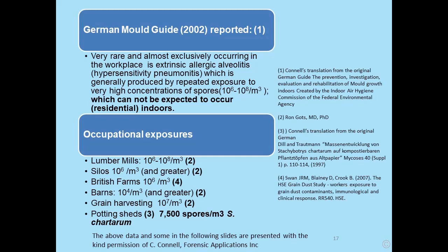Well, the German Mould Guide reported that hypersensitivity pneumonitis is generally produced by repeated exposure to very high concentrations of spores. In simple terms, that's 1 million to 100 million per cubic meter, which cannot be expected to occur in residential properties indoors.